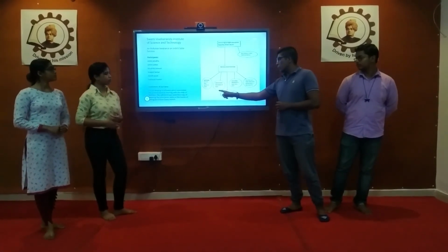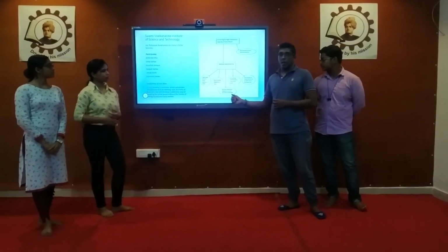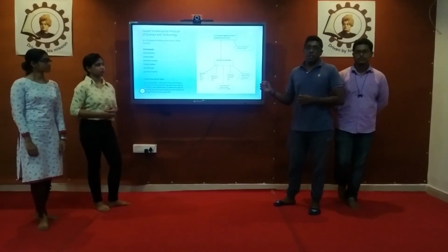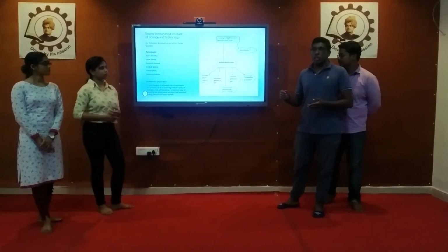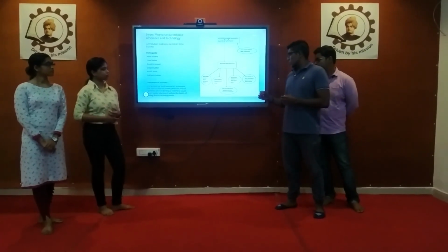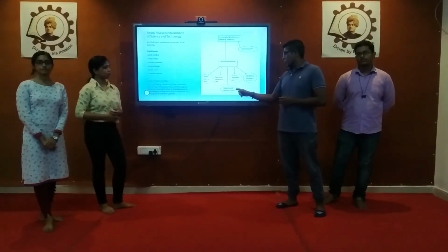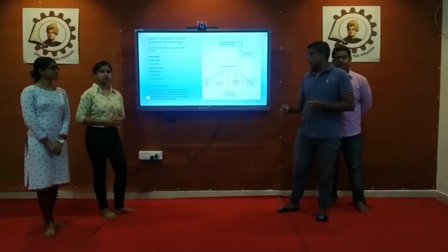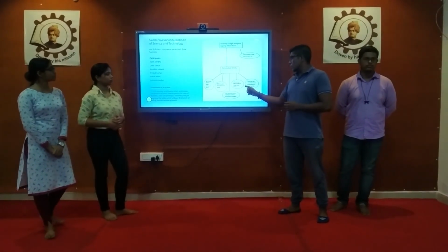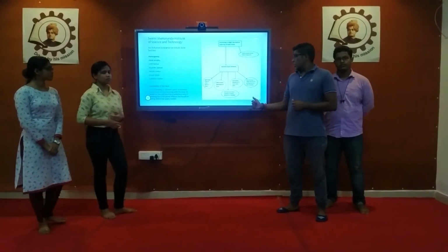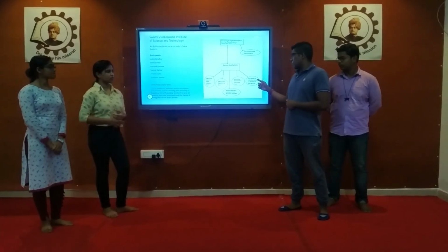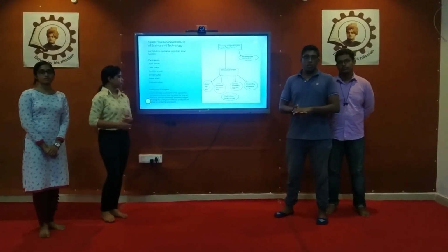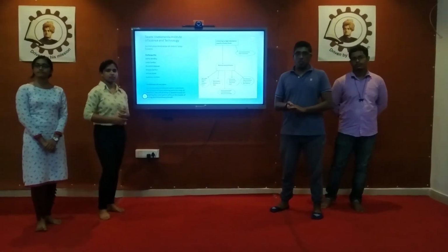We can install a lightweight robot on the surface of the panel. The second one is electrostatic repulsion of dust, using variable load voltage to push the dust off the solar panel. The third one is anti-dust solar panel coating to increase the absorption of sunlight, and we can also change that after 5 to 7 years. The fourth one is automating the windshield to clean the dusty panel. And the fifth one is we can slope the solar plate for the rejection of dust particles. That's all.